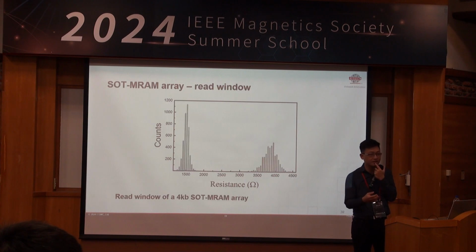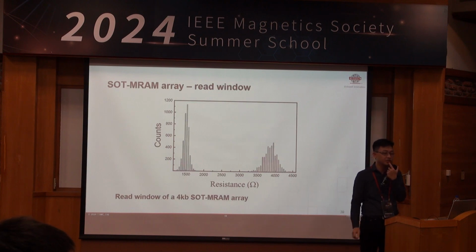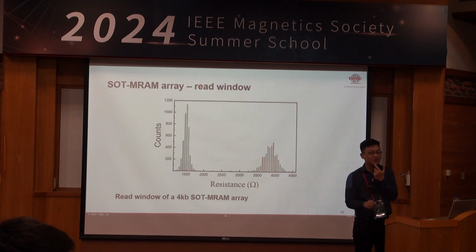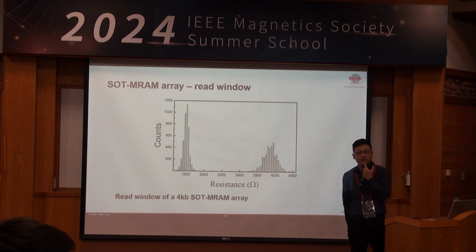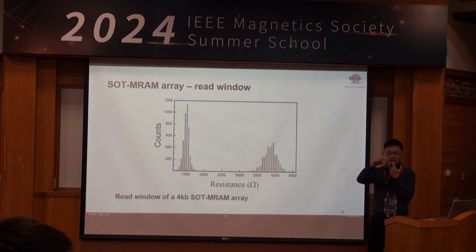For example, Chi-Feng's group has a lot of different alloys, including platinum, chromium, platinum, cobalt, something like that. We're still trying to integrate them into the bus. But platinum for the MTJ is not so friendly, so you will suffer from other issues. But I think you can find a reference paper about using platinum as a sealing layer. Okay, thank you very much.